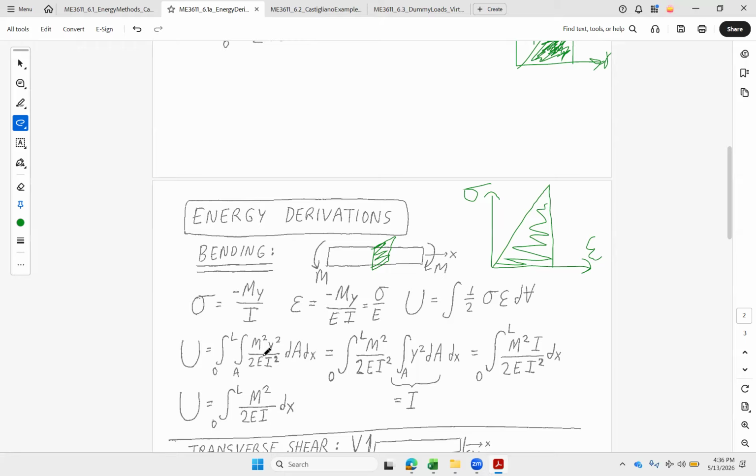All right, we've made function moments before. We've done shear and moment diagrams. So M of x is not too hard for us to come up with. And we'll just have to FOIL it, square it, and integrate it out. Usually it's a polynomial for M, so it's not too bad to just do the chain rule going up piece by piece.